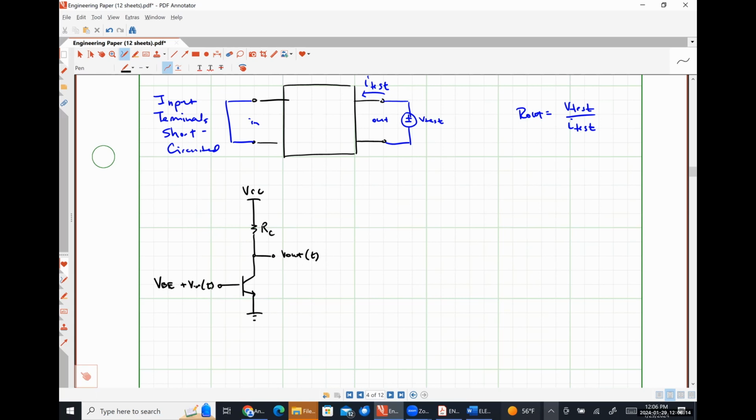For our small signal analysis, so that we can figure out our small signal voltage gain, our small signal input resistance, and our small signal output resistance, we need to turn off our DC sources, much like we did earlier. And then we're going to use our small signal model. Let's make this even easier, and let's say that early effects are not present.